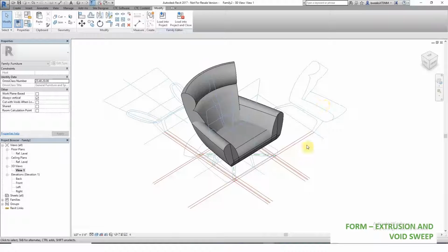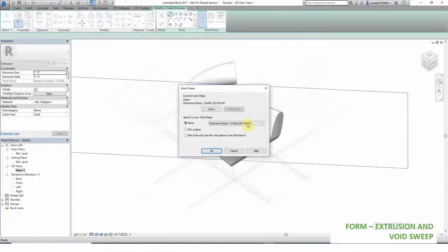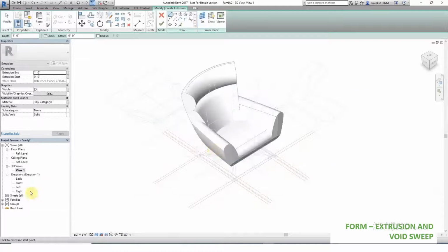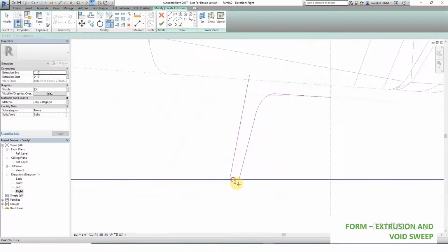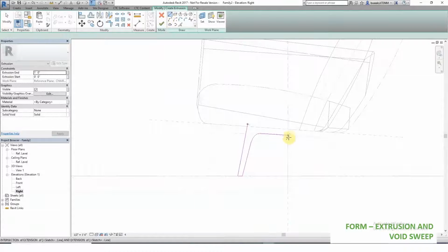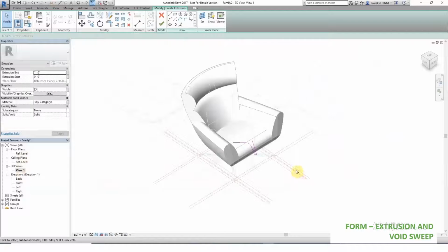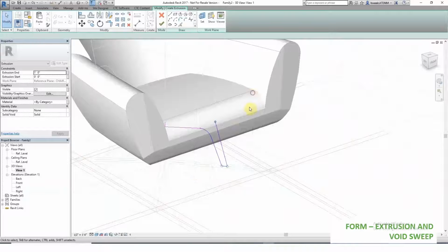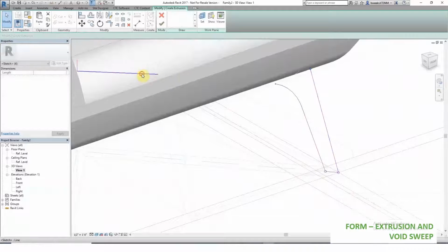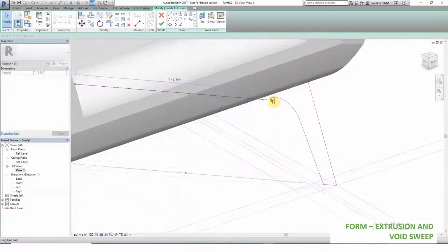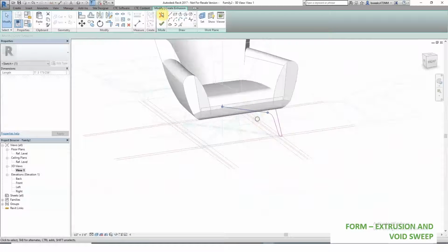Now this is going to create the feet, the legs of the chair. I kind of cheated a little bit. I saved some time. I went ahead and inserted the CAD elevations off camera, and then I drew some model lines to reflect the true leg locations, because as you can see, when I select the outlines of the legs that were drawn in 2D elevation, when you select them in 3D, they actually don't quite line up. So what I have to do is just old-fashioned lines off of the plans and elevations to get my legs in the right position.